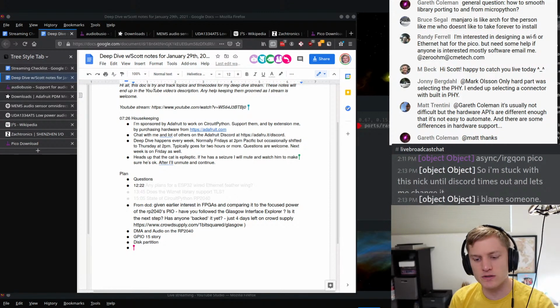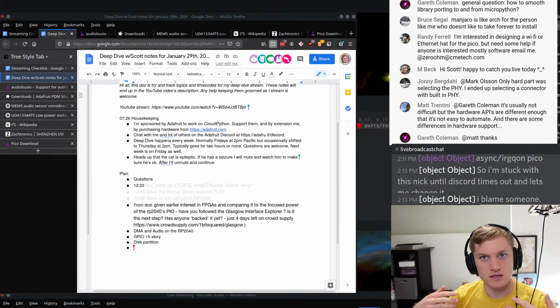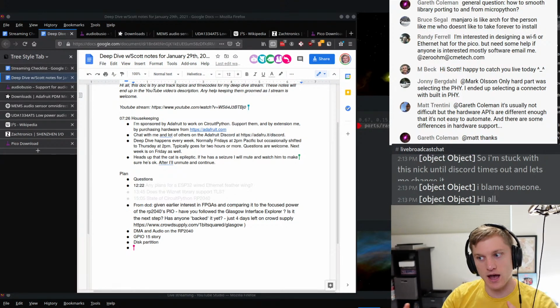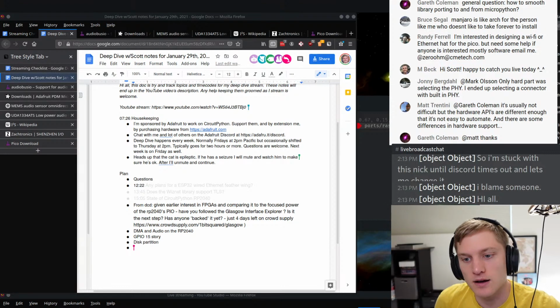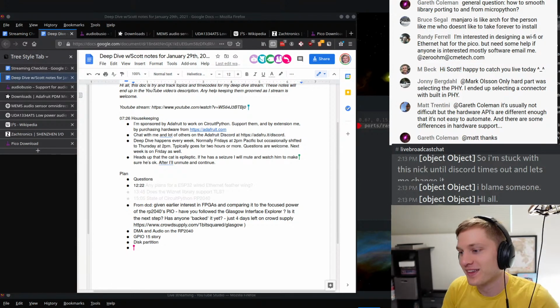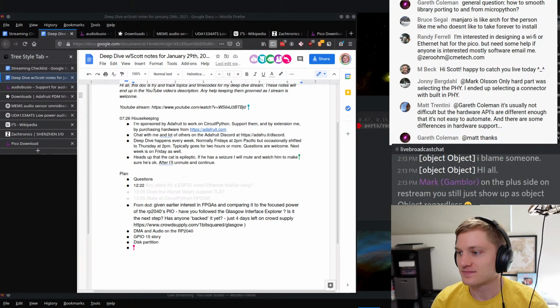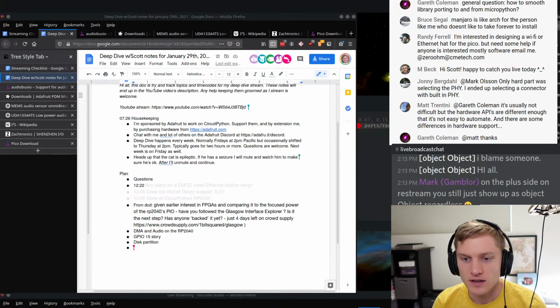So yeah, there's definitely work there to do, but a lot of what we do when we design APIs is start from the very minimum with what we know we need, which is what I did for PIO for NeoPixel, and then we'll add stuff to it as we find that we need it. For example, for PDM in, I'd love to be able to test it with the RP2 PIO interface, and therefore I would need to read some bits. And so I'll probably just add that. So yeah, that's kind of the PIO stuff.